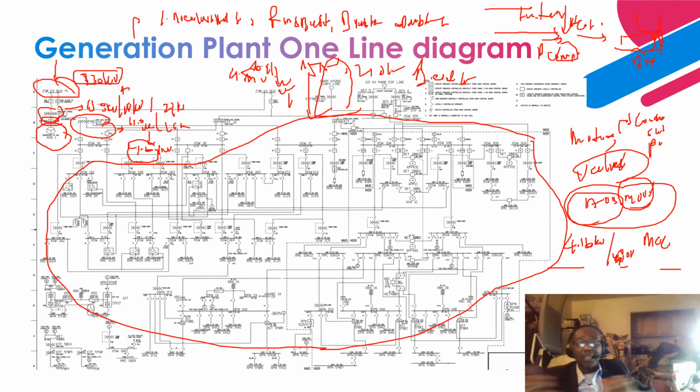If you should lose that dedicated source to start up the plant, it goes through an automatic throwover switch and is able to start up the standby or emergency generators, to continue to provide auxiliary power to all this equipment that helps the generator turn on and start generating power.